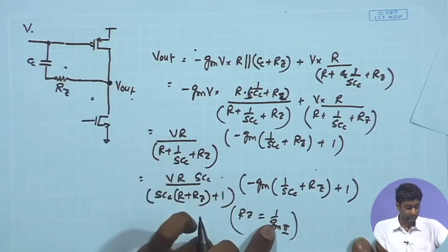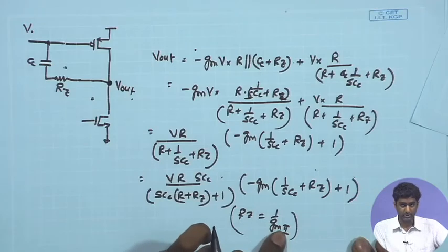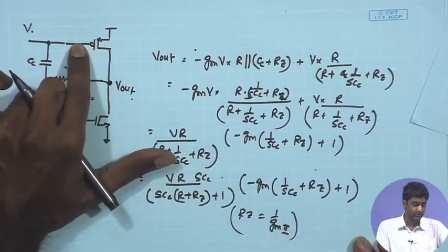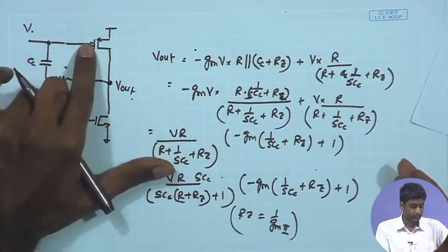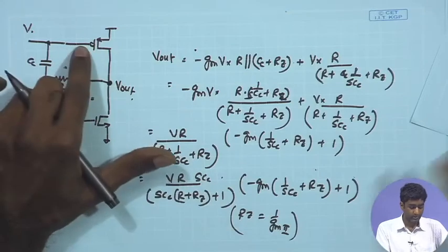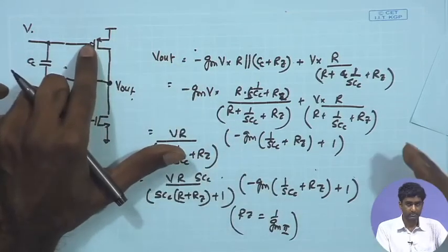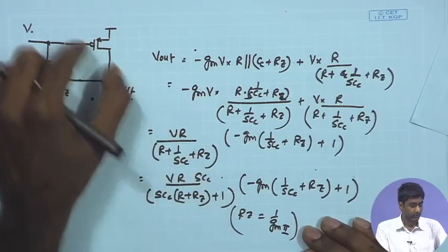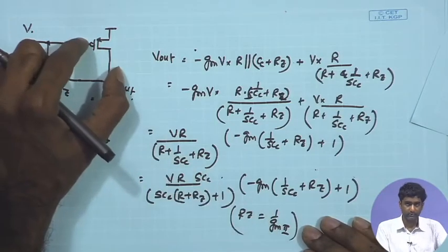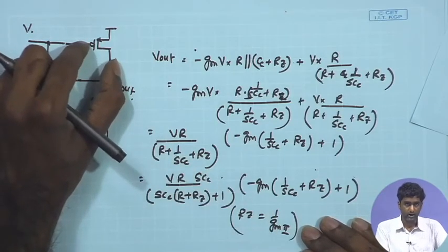You can have plus minus 50% or even 100% change in the Gm. If in simulation you set up this value of Gm to be 10 to the power of minus 4, in the actual design you may get a value which is 2x or 50% of that. So, you can have a wide range in the values of Gm that you get after fabrication,